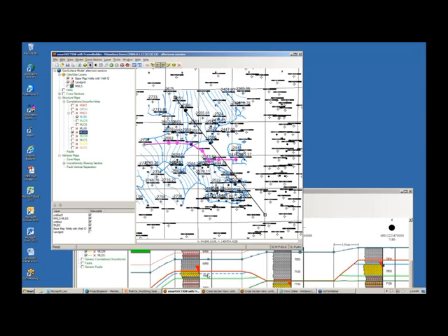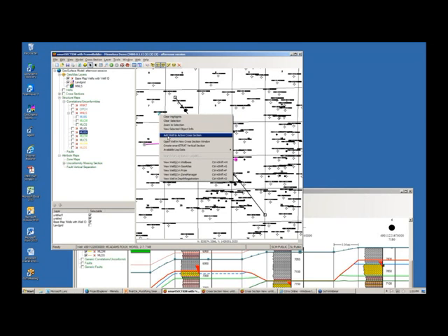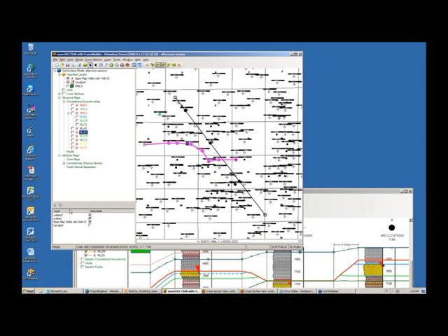John, any last question? There was one individual who was trying to follow along and who was having trouble making a well-to-well cross-section. He didn't realize that when that little flyout box popped up with different map entities on it, you had to click the well ID, and I just mentioned that in the lower left-hand corner of the map view, you've got a selectable dialogue, and you can uncheck everything but a wells layer, and that way you won't have that issue with other entities popping up when you're making a well-to-well cross-section. And you also want to put that well layer up on top here. Yep. So it's the first item selected.